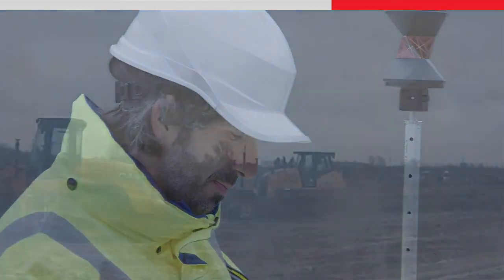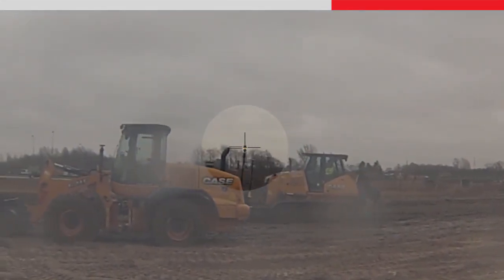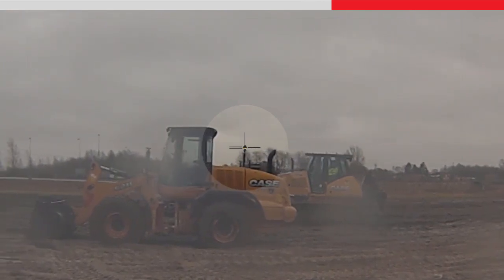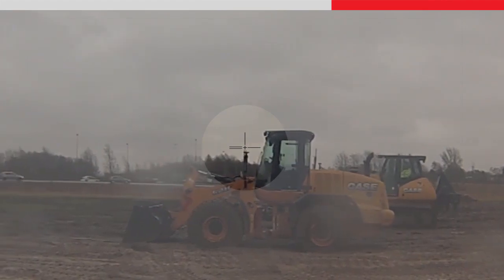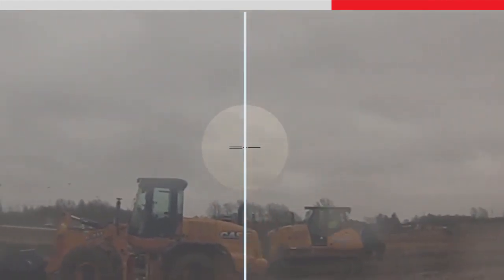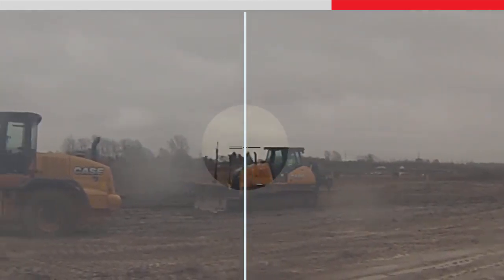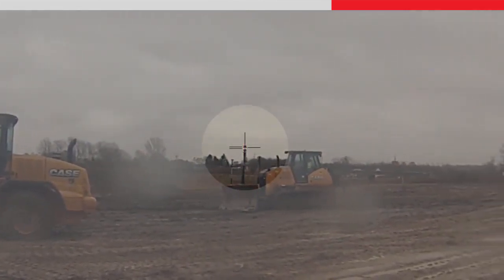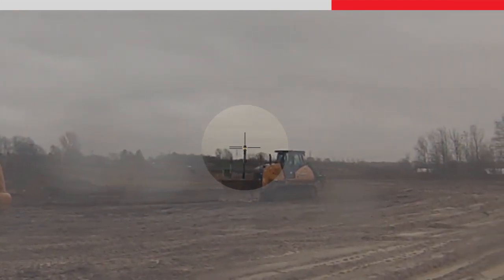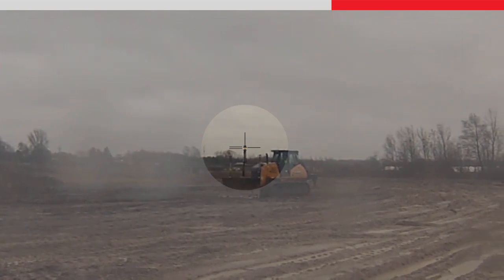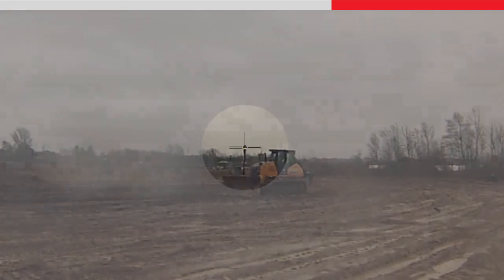Imagine now a multistation is being used for machine control and a target is being followed on a dozer. The dozer moves behind another machine and the instrument loses lock to the target. The dozer stops and drives back in the opposite direction. A cube search will start and the instrument will find and lock onto the target even with the dozer still moving. Again, this is a massive time saving because the dozer driver does not have to stop the machine and wait for the instrument to lock to the target.